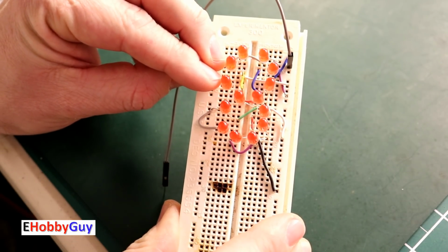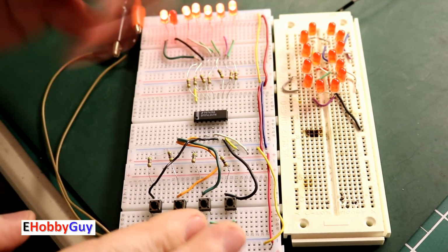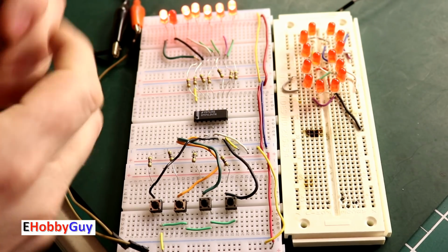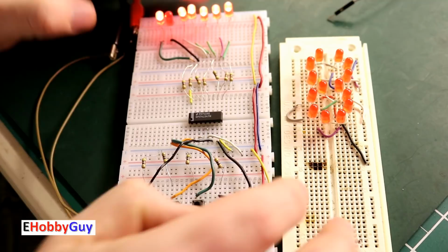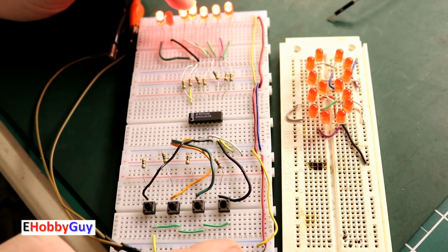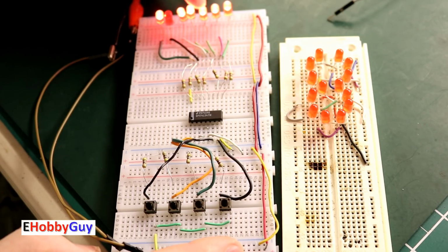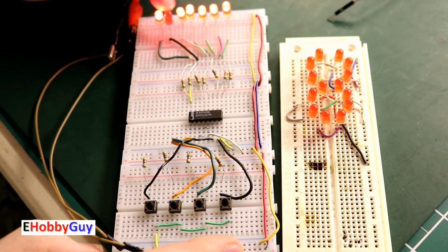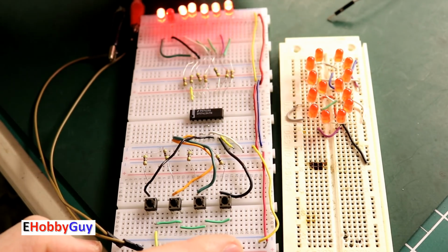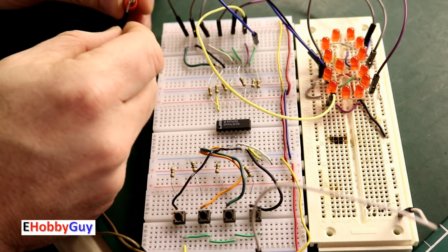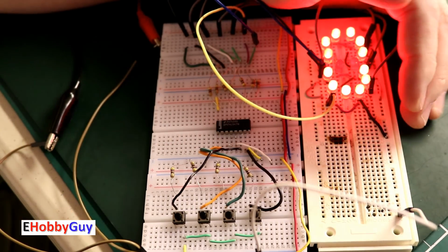And this way, when I get a signal in, it's going to trigger both LEDs for that particular segment. So right now we're at a juncture where I have these in the order in which they're just pinned out here, just for clarity to show you that they do light up. It's clear to follow them through. So what I'm going to do is take these away and jumper each one of these. It starts, I believe, here, A, B, C, D, E, then F and G. Going to jump them over to the segments on my own 7-segment display right here. I'll give it some power, and we should get a 0, and yes, we got a 0.